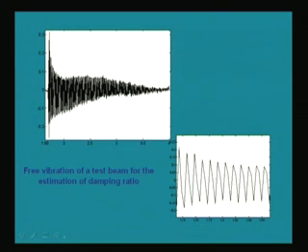This is another typical data which we have captured, especially when we gave a tap or impact to a simply supported beam, and we measured the decay of the vibration. So you can see here we give the tap or hammering to the beam, and then gradually the vibration is decaying. A close view of some part, maybe up to this, has been blown up here.